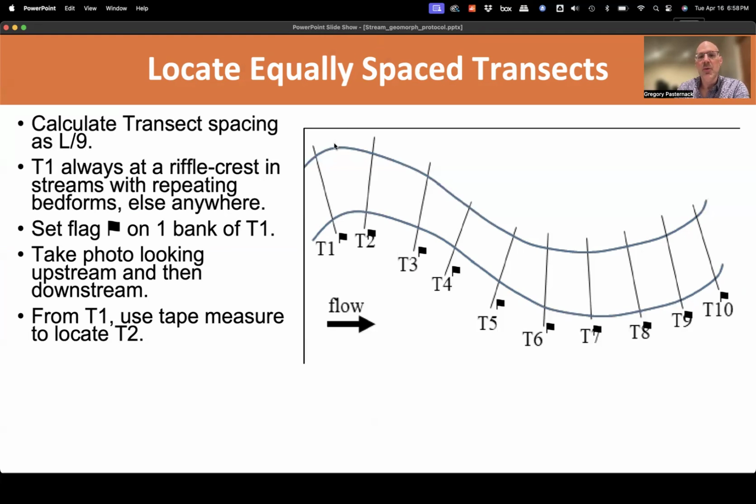You may be at one site where the left bank is just a steep cliff covered in blackberry thorns, and there's nothing you can do. We have to be somewhat pragmatic, like what will work at a site. I wish we could perfectly standardize everything the same everywhere, but it isn't realistic. So pick a side and measure the distance all along that side, at least consistently there as best you can.